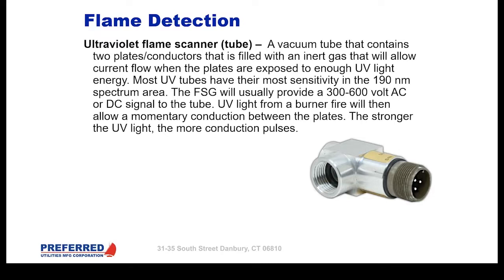When there's enough UV energy from a combustion process, that tube is subjected to that, it will provide a momentary conduction between the two plates. In other words, kind of a pulse, which allows that voltage to jump across to the other plate. The stronger that light is, the more conduction; in other words, the more pulses.